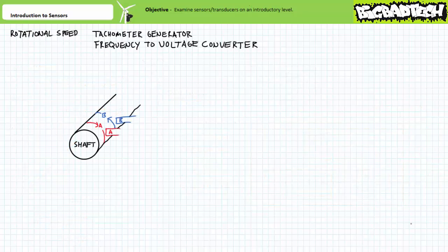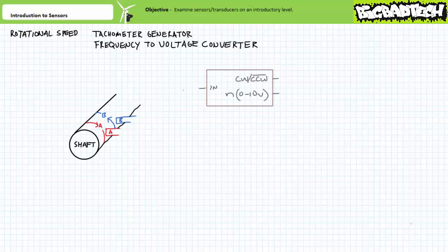With very little effort, a rotational speed sensor can also indicate not only magnitude, but also rotational direction. Consider a system that employs two tags, A and B, ever so slightly offset from each other on the shaft. If stationary switch A and switch B are in line with one another, and A is triggered before B, the shaft is obviously rotating in one direction. If switch B is triggered before A, the shaft is obviously rotating in the other direction. Such a system measuring both rotational speed and direction can represent the two related quantities using a couple different formats.